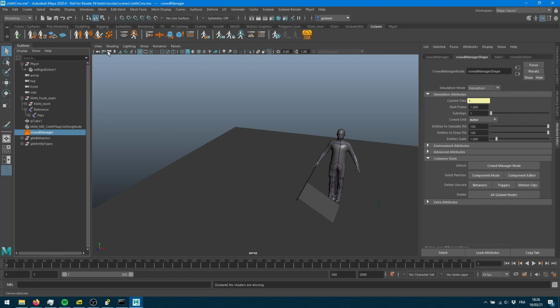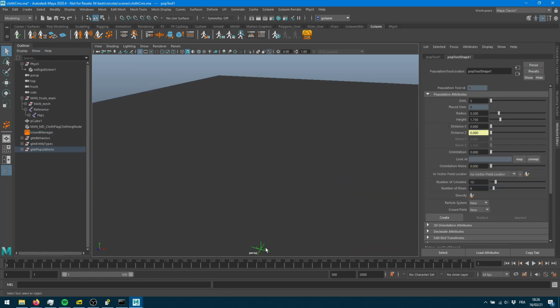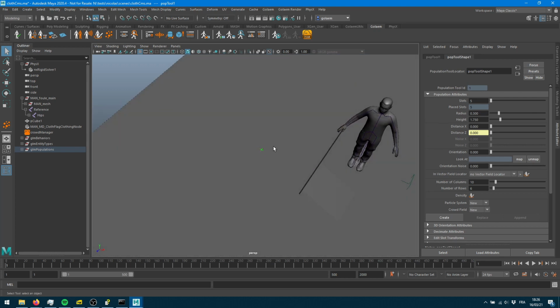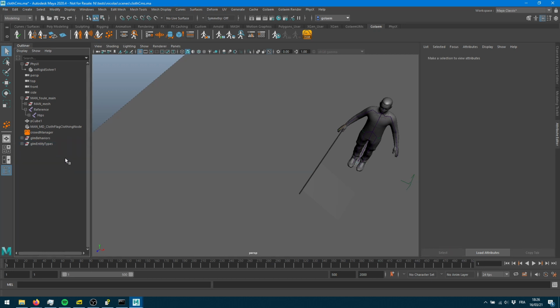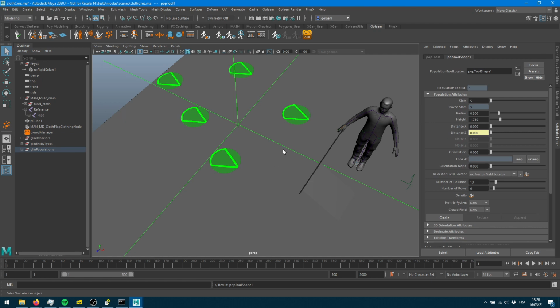As a note, if you don't set up to centimeter, when you create your population tool, you'll notice that it's super small and it has a super small radius. So it usually means that those are not being aligned properly. So let's remove this. If we set up our unit properly to centimeter and we create a pop tool, now we'll get something which is scaled properly. And same goes for the gravity and all the physics parameters at the same time.